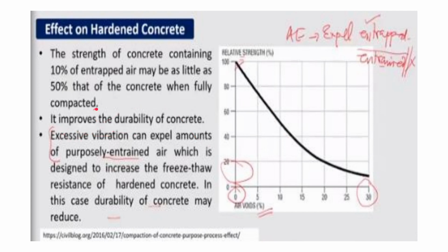However, a little amount of entrained air is required for freeze and thaw resistance and workability. The question is of durability. It improves the durability of concrete, because of the freeze and thaw resistance, so a little air is required.